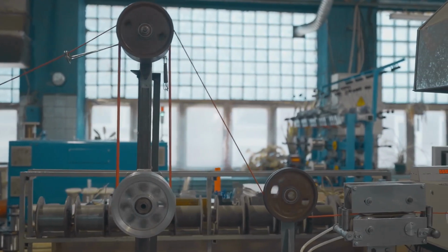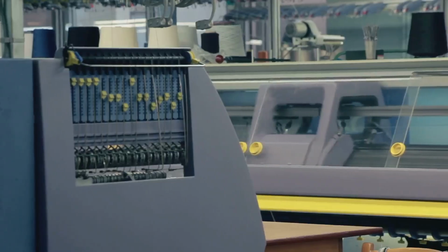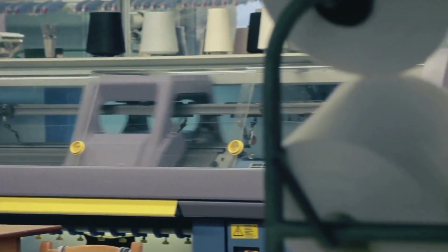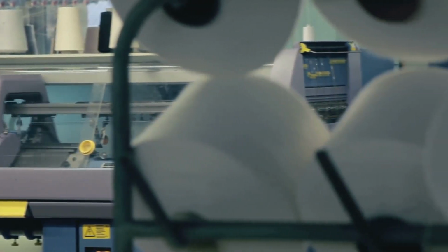Think of millions or even billions of relatively small stress cycles. In these cases, the material behavior is predominantly elastic. There's very little, if any, plastic deformation occurring at the critical locations. It's simpler, often requiring less detailed input.